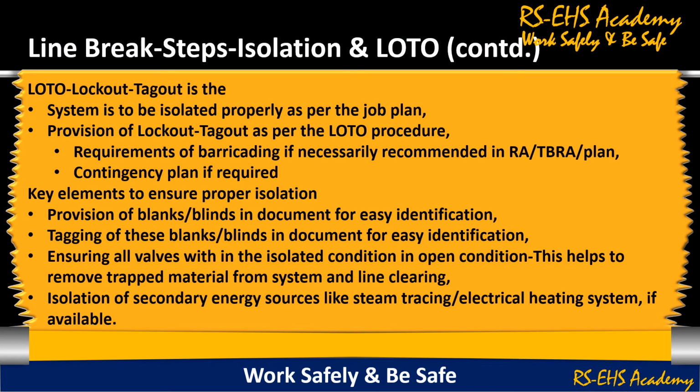Line break step: isolation and LOTO. LOTO, that is lockout tagout: the system is to be isolated properly as per the job plan. Provisions of lockout tagout as per the LOTO procedure. Requirements of barricading if necessary, as recommended in risk assessment or task-based risk assessment or plan. Contingency plan if required. Key elements to ensure proper isolation.